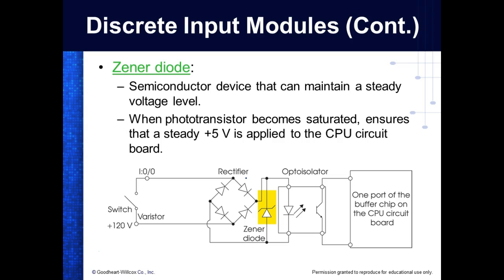So if your input module is designed around 10 to 30 volts AC, and you put 120 volts in the thing, what's going to happen? Well, it's going to bop it, right? But it's not going to bop the PLC. It's going to get that module or that input. If you got a DC input and you put AC on it, then you got big problems, right? You understand that? So that's all you got to know.